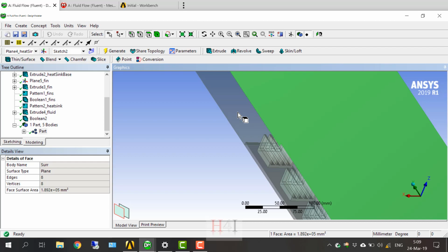Of course, this means that the mesh will not connect at each other at the interface between them. But the mesh is very fine, and Fluent can handle this. There is something in Fluent called interfaces which handles this, the not connected mesh. Fluent can handle this. If the mesh is good and very fine, the error will be very small.